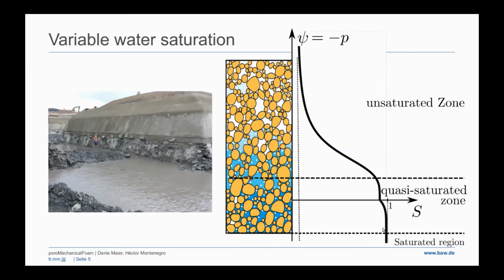However, if you're getting closer to the groundwater table, the likelihood of there being entrapped gas bubbles inside the pore space becomes quite high, and so the saturation becomes a function of pressure. When you're above the groundwater table, the water is mainly held in the pore space by means of capillary action, since the pressure falls below atmospheric pressure.